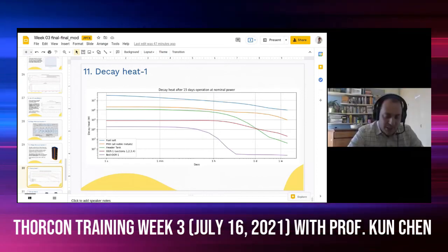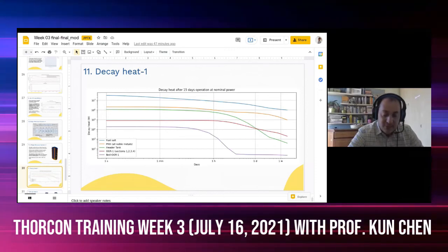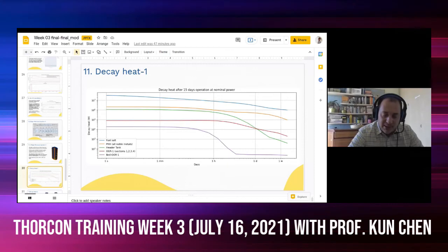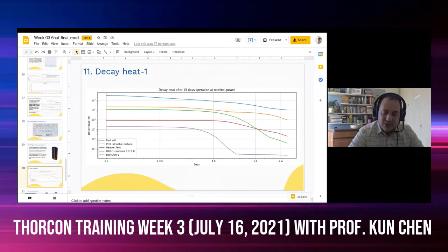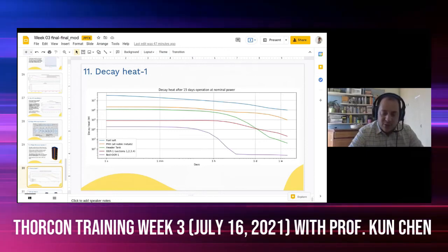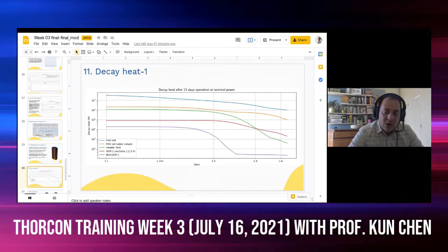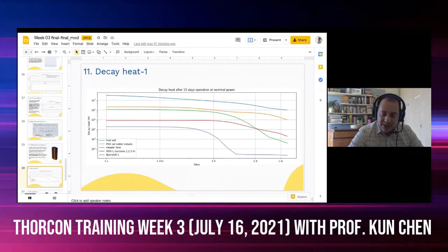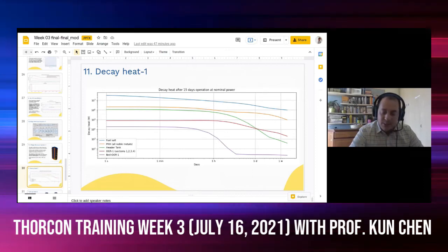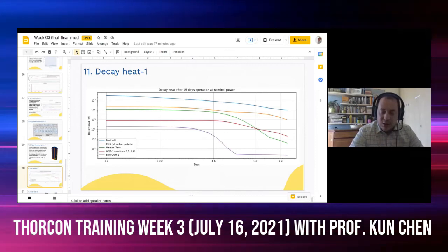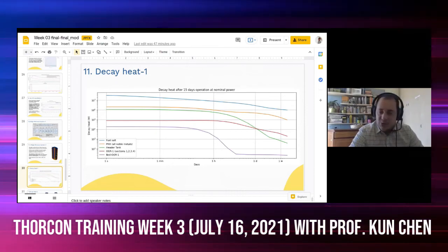Yeah, in the gaps between logs, when graphite shrinks, the space for the flow increases, and so locally the pressure drop decreases, and the flow rate in that channel with respect to the rest of the core on average increases. So there is a small redistribution of the flow rate throughout the core due to the change of the thickness of the gaps between logs due to the shrinking of the logs. It has to be taken into account. It does not have a huge impact.